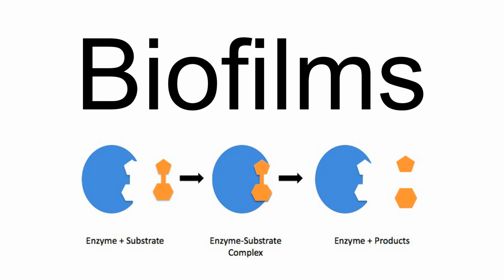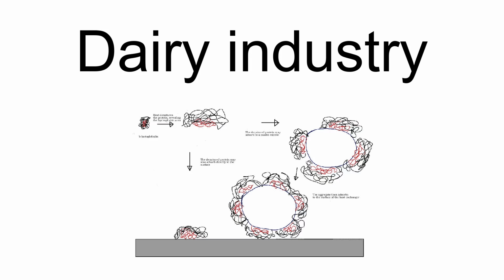Thermal treatment of milk by indirect heating, e.g. pasteurization, to reduce microbial load and increase shelf life is generally performed by a plate heat exchanger. Heat exchanger surfaces can become fouled by adsorbed milk protein deposits. Fouling is initiated by formation of a protein monolayer at room temperature, followed by heat-induced aggregation and deposition of whey protein and calcium phosphate deposits. Adsorbed proteins decrease efficiency of heat transfer and potentially affect product quality by preventing adequate heating of milk.